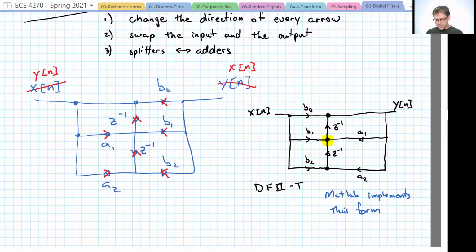If you have something that's maybe running in fixed point or finite precision of some form or other, and basically anything in a digital system has finite precision, then causing it to blow up first might cause it to saturate, at which point bringing in the 0 will never fix anything. The damage has been done. By putting the zeros first, it brings it down, preventing saturation, then the pole could bring it back up.